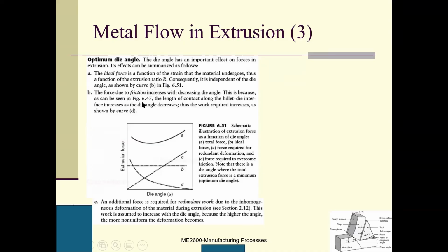Why? Because from figure 6.47, the length of contact along the billet-die interface increases as the die angle decreases, and thus the work required increases, as shown by curve D. Additional force is required for redundant work due to the inhomogeneous deformation of the material during extrusion. This work is assumed to increase with the die angle, because the higher the angle, the more non-uniform the deformation becomes.